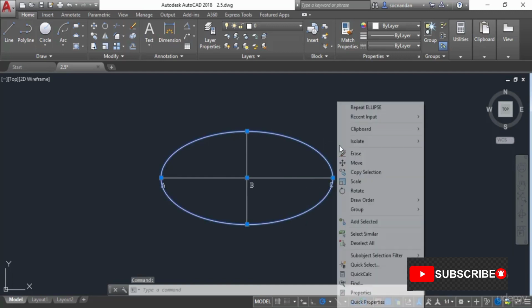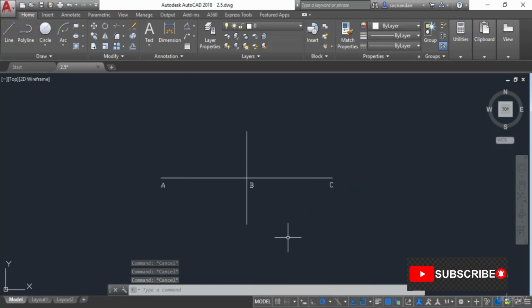So now let's erase this one as well. So now let's have a look at the elliptical arc. So for that I'll once again go to the flyout, and here we have this elliptical arc option. So let's select it, and now in this case also we need to first make the ellipse and then we'll convert it into an arc.